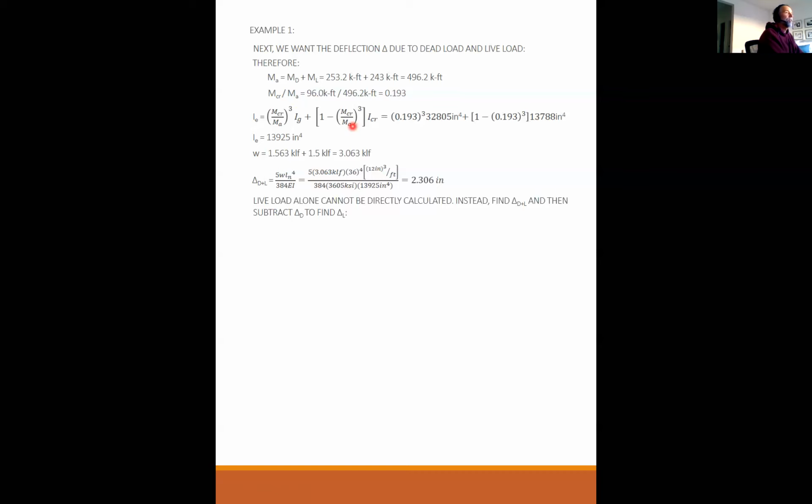It's always accompanied with the dead load. And the dead load already pushed the concrete past cracking. So the entire stage of live load is on a cracked beam. So if you just evaluated the live load alone, you've negated all of the effect of the dead load already cracking the beam, and you'll just have completely the wrong answer.